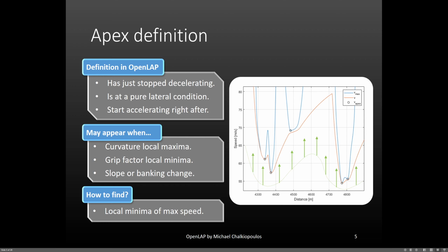You can think of this speed trace as a rope that is allowed to touch and wrap around bumps created by the blue curves, but is not allowed to move them. This will make it hang in mid-air between the bumps in a sense, showing us the vehicle's combined performance. What the engineers try to do is move the blue curves upwards and make the rope more flexible, increasing the area underneath it and subsequently the vehicle's performance.